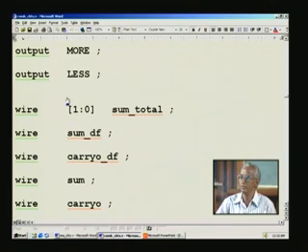For example, a microprocessor bus signal, any signal that you want to have, you can treat that as a wire as such. It's a physical wire connection, that's why they have retained this name wire. And once again you see multi-bit represented in similar fashion, followed by the actual signal name. And these signals may be an output straight away appearing at the output of your design module, or it can be intermediate outputs as such, used in subsequent sequential circuits, etc. And so is the case for other variables.